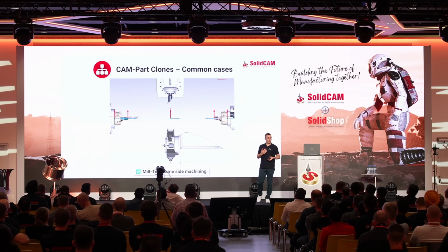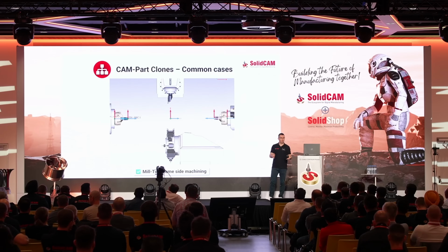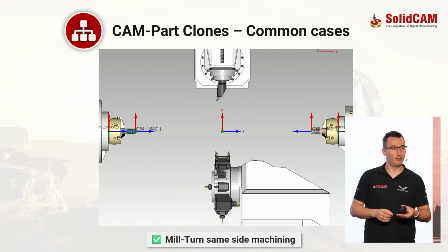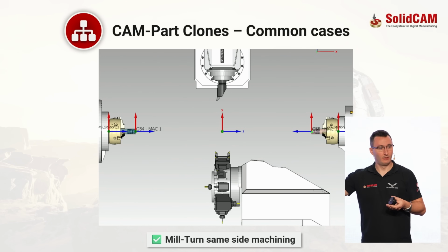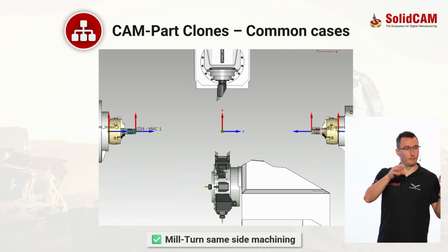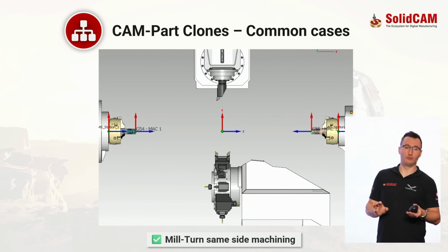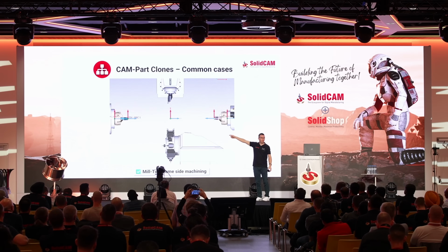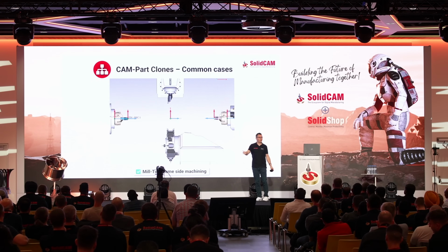It's important to not just mention that clones are applicable only for milling. No. I was asked many times for the feature where I have 1 part that is actually machined on only 1 side, that's it. You do the cutoff, the part is done. But I want to use also my sub-spindle to have 2 workpieces done in the same program. I don't want to use add a new workpiece, I just want to use the same workpiece and also get 1 program, 2 workpieces done. We were not able to do that in SolidCAM. With clones, you can do that. Create all the jobs there, super, clone it, G55, G54, 1 program, double jobs, that's it.